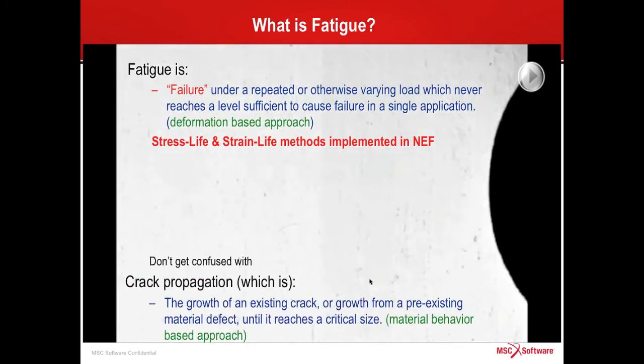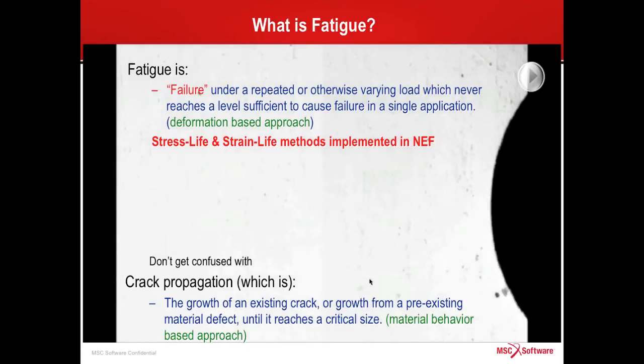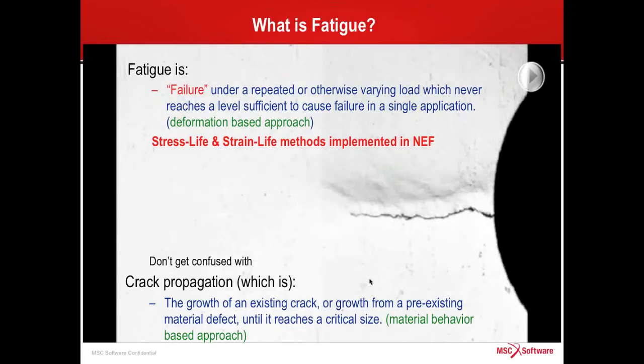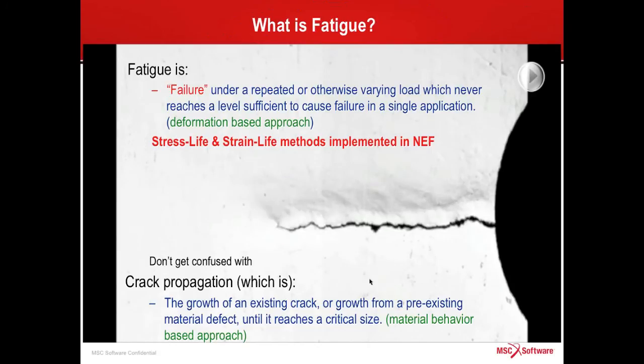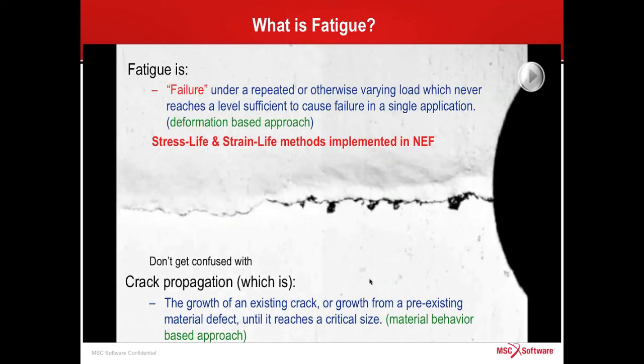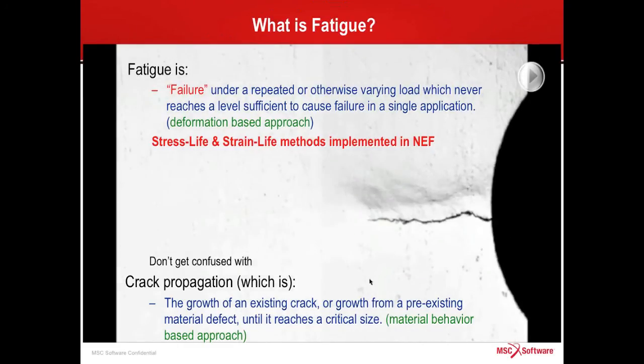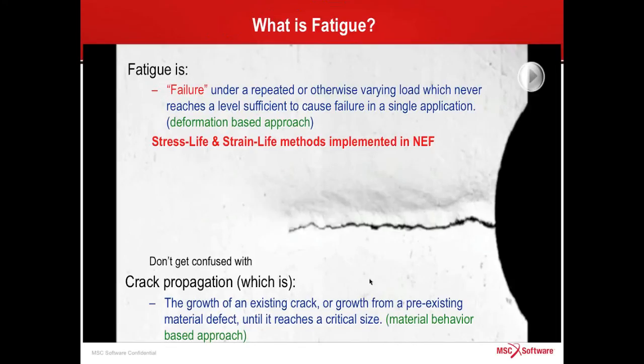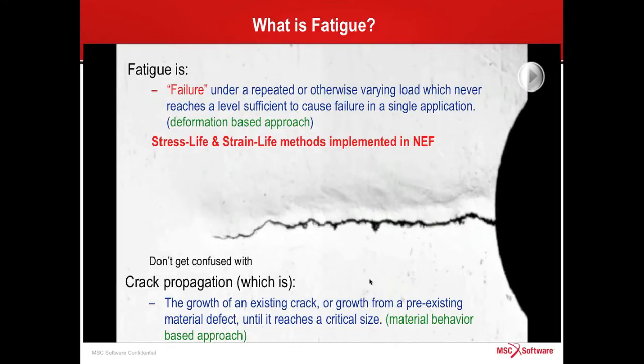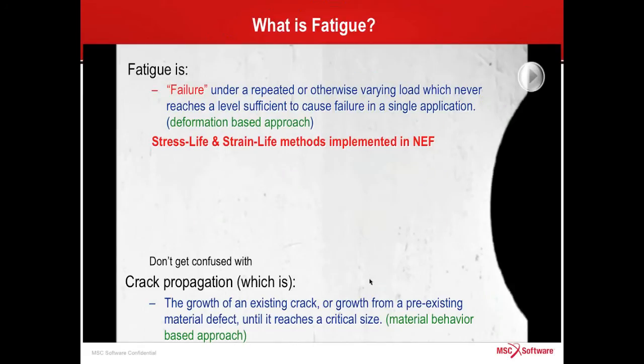There is an alternate approach, which is to do a crack propagation type calculation, usually coupled with some kind of damage-tolerant design philosophy. And that approach is much more sophisticated, but that's not what I'm talking about today, and that isn't what we've embedded inside Nastran. Now, there is no fundamental reason why that can't be done in the future, and that may well be something we look at. But today I'm going to talk about conventional fatigue methods embedded inside the solver.